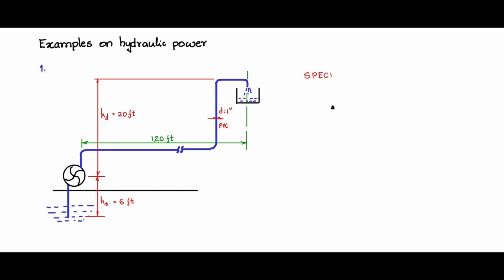So let us put down some specs for which we can calculate the hydraulic power. First is Q, discharge volume. So the discharge volume most of the time would be the size of the overhead tank. Now let us say you have a 1000 liter tank. So let us say we want 1000 liters, and how soon do you like it to be filled up?